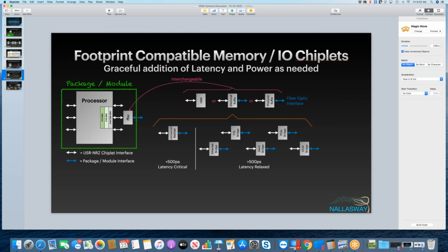So that's the idea. But yes, they would be a standard footprint, or maybe you could put multiple smaller dies on the same footprint as the HBM die, depending on the channel breakup. I think HBM is 8 channels, so maybe you could put 8 individual buffer chips on the same footprint as one HBM. So it can be sliced a lot of ways. Obviously, that's part of the challenge, is how you define a footprint that can support all these scenarios.